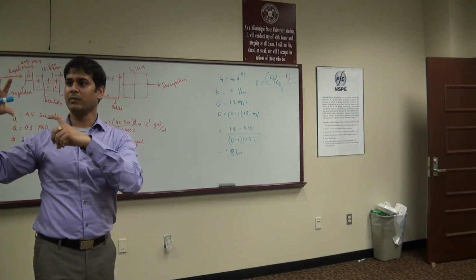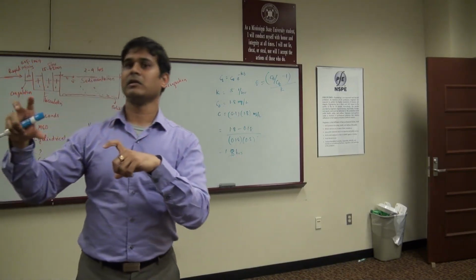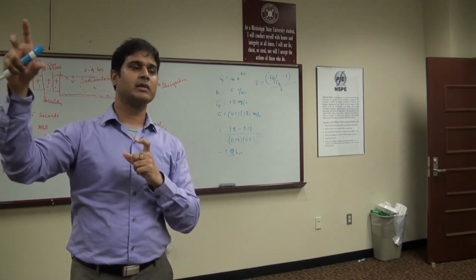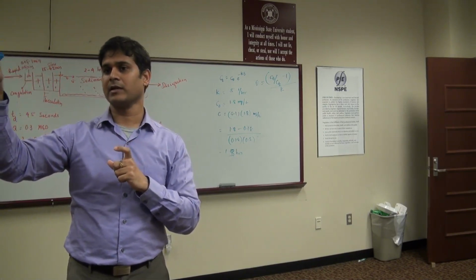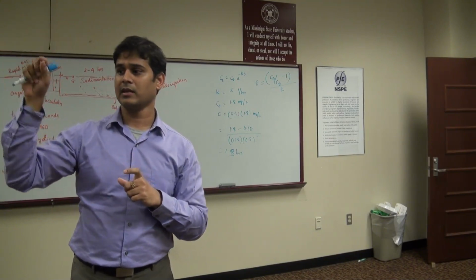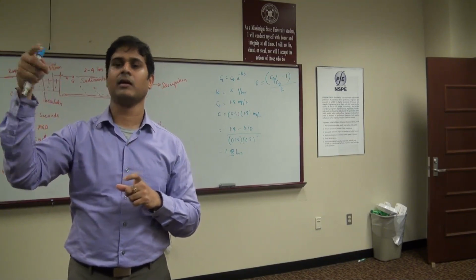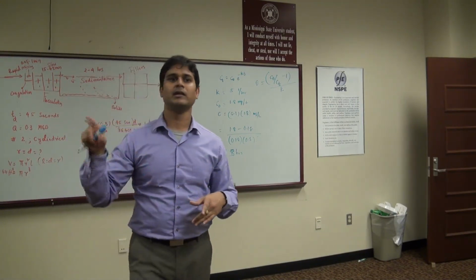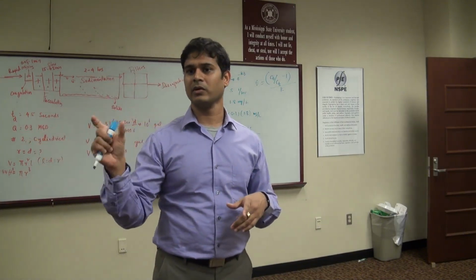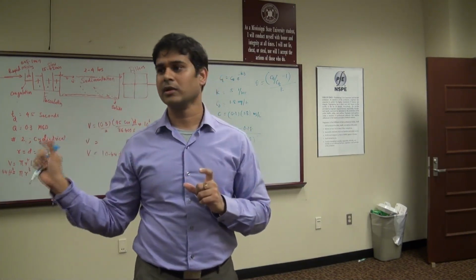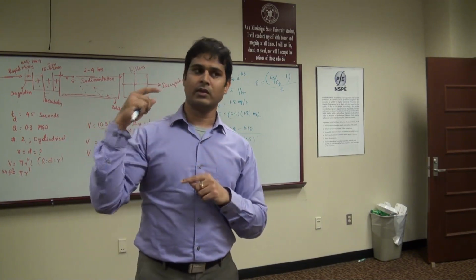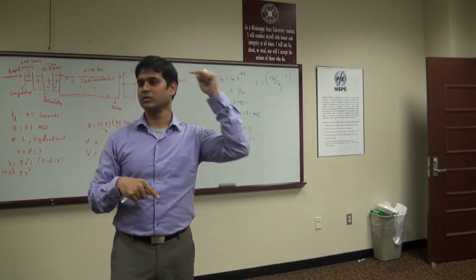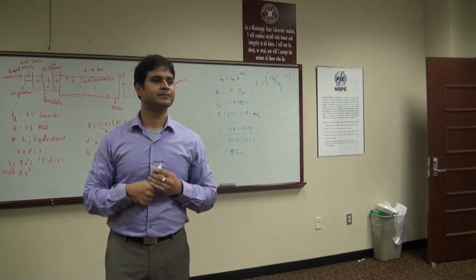So in the two tables, in the exam you want to pay attention that you're using the right equation from the right table. The first one is about the detention time or the hydraulic retention time. It's theta, and on the top it says theta. The second one is for concentration. Honestly, I didn't see the complete mixed reactor word over there, so I was confused why that solution came up that way. So you have to pay attention to what it is asking, then look for the right equation in the tables.